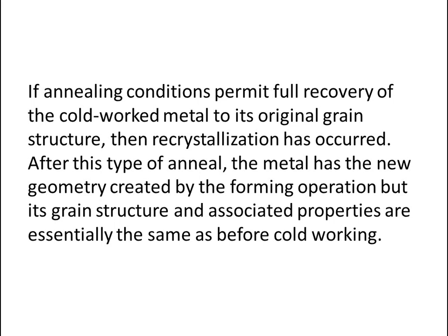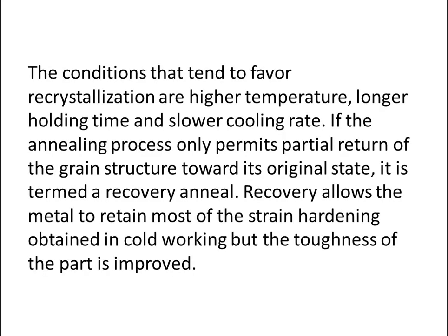If annealing conditions permit full recovery of the cold worked metal to its original grain structure, then recrystallization has occurred. After this type of anneal, the metal has the new geometry created by the forming operation, but its grain structure and associated properties are essentially the same as before cold working. The conditions that tend to favor recrystallization are higher temperature, longer holding time, and slower cooling rate.